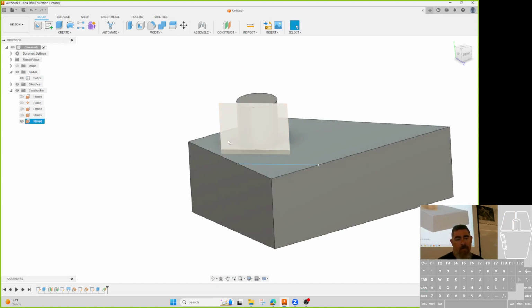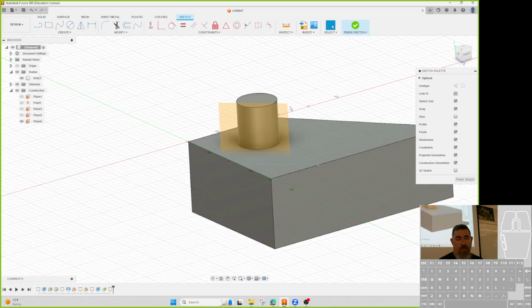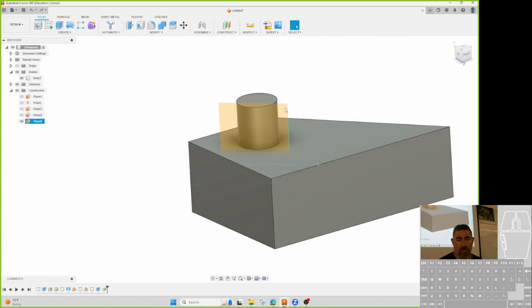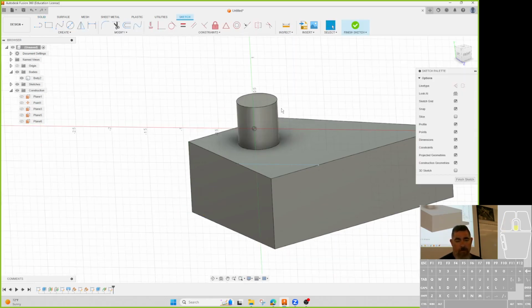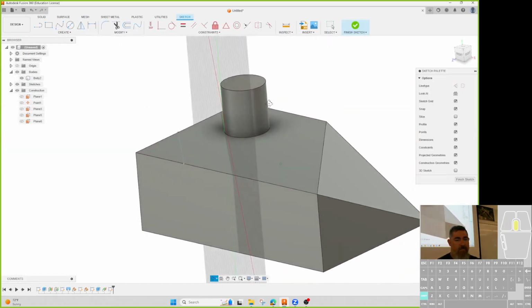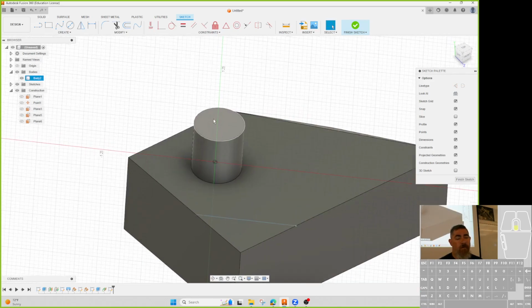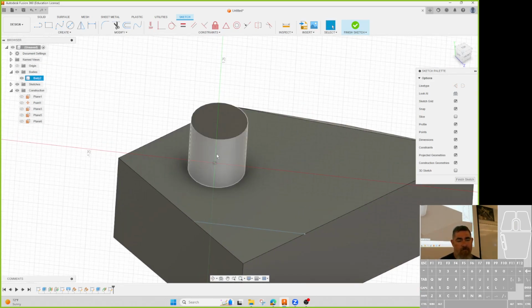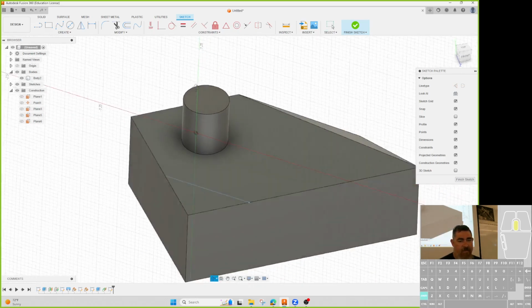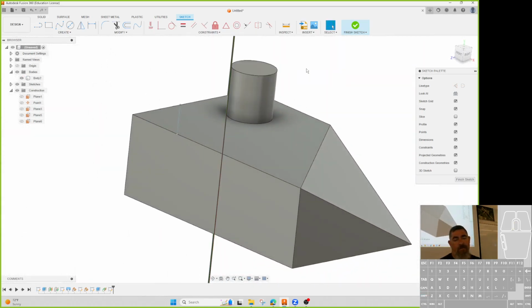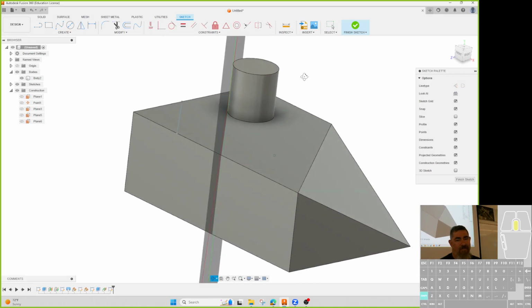Okay. And now I can make a sketch and put my center point, right? So create a sketch. Oops, wrong plane. Sketch. There we go. And I can look and see that, yes, my sketch is on that plane that's tangent to the cylinder. So how do I make something for a hole that's halfway down there that's centered up on the cylinder? Intersect the geometry so you get the relevant lines. Can I intersect it? Is it crossing the sketch plane? It should be because it's tangent.